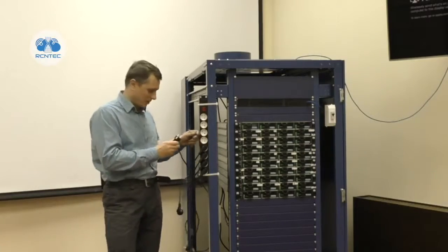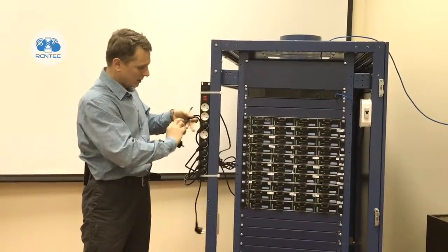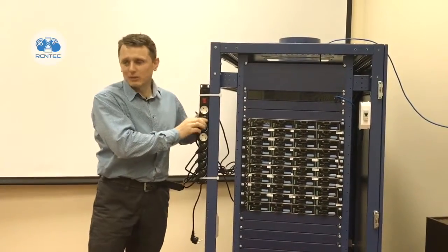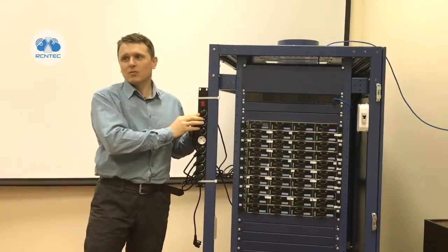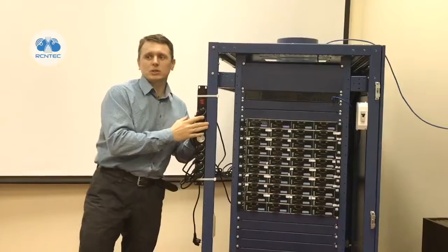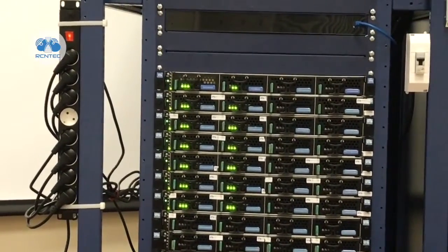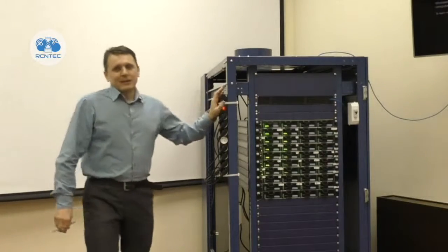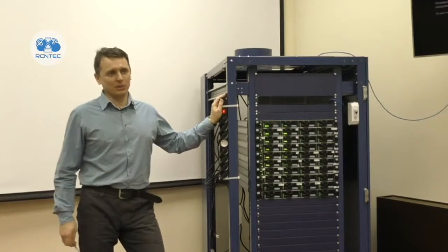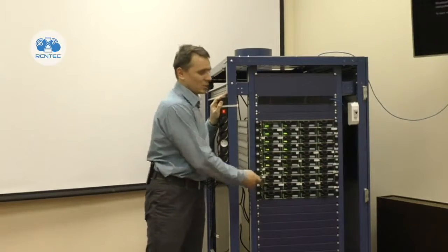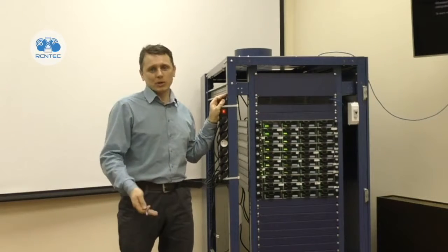Luckily this time we know that this particular device is the cause of trouble, we disconnect it, connect the rest of equipment, and after resetting the circuit breaker again, we'll finally restore power supply. That's what I'm gonna do now. So, finally, we've managed to provide power to all equipment, except for the device that has caused a short circuit.